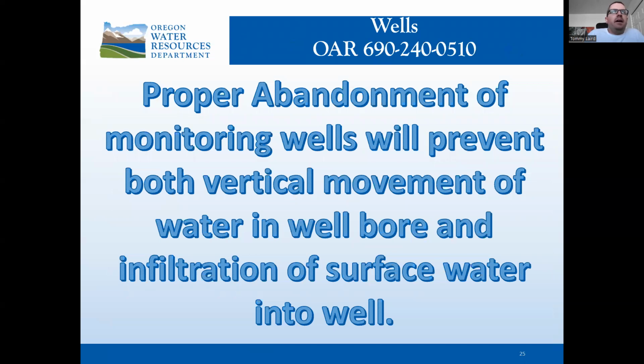We'll cover proper abandonment of monitoring wells. This is OAR 690-240-0510. To properly abandon a monitoring well, it's done to prevent both vertical movement of water in the well borehole and infiltration of surface water into the well itself.